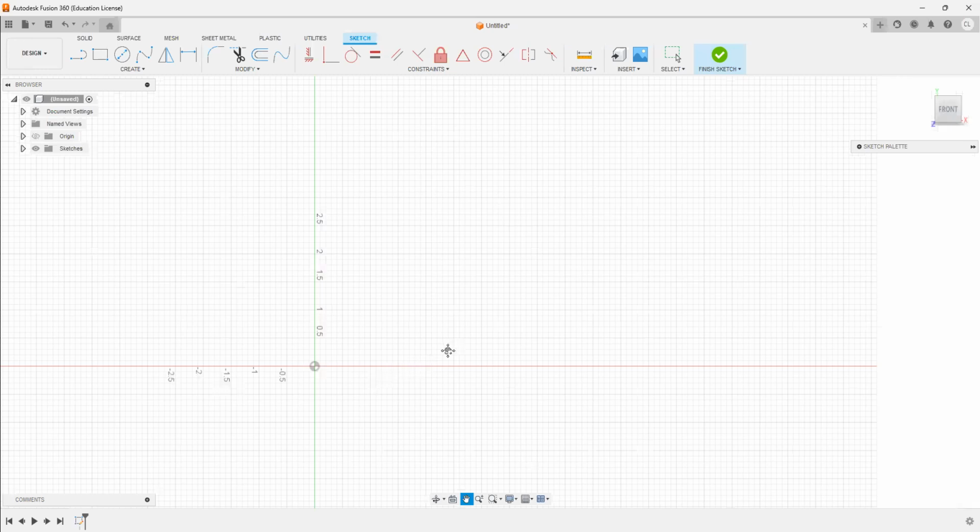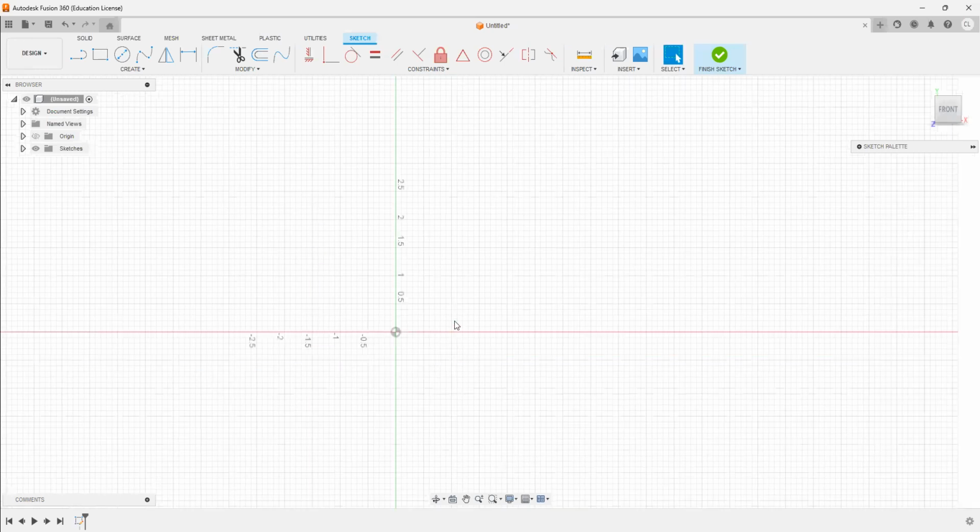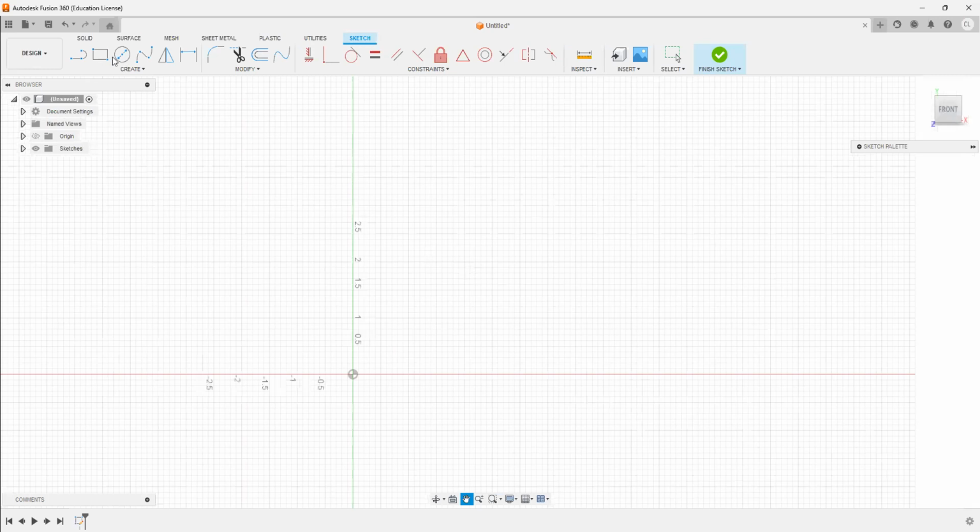Today's Easter egg is going to be a little bit different, very useful when you need to see opposite sides of the object. But I digress. Let's move forward. So with our first tool, we're going to use the rectangle tool. I'm going to go with my front view sketch of 2, or actually that's height. So that's going to be 0.5 in height and 2 inches across.